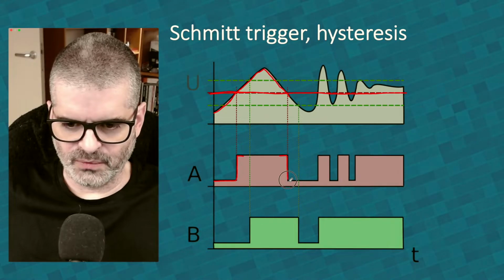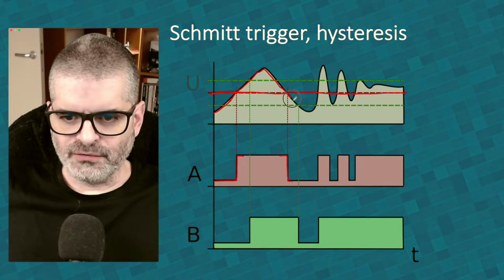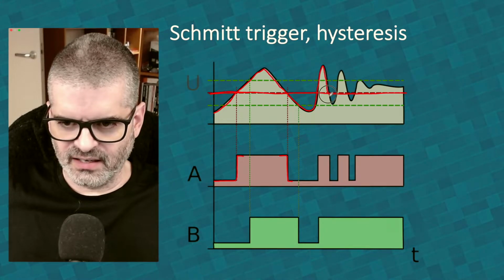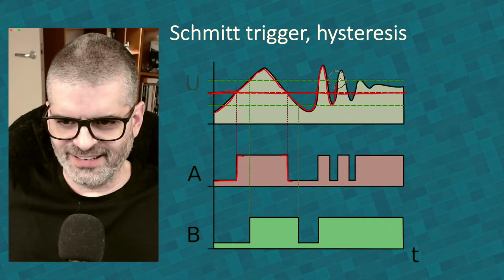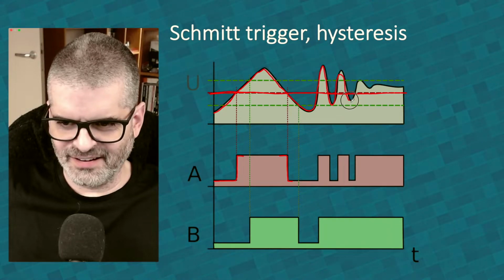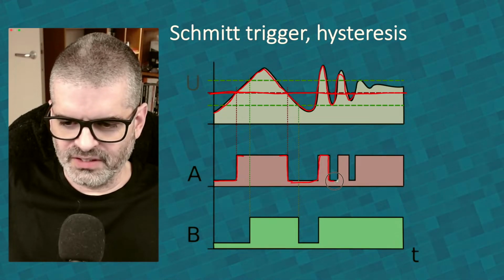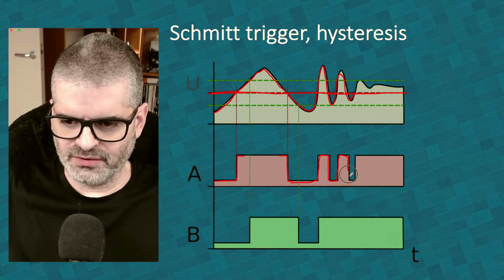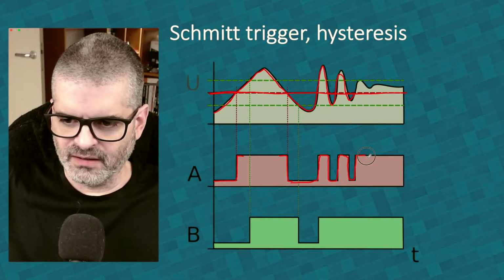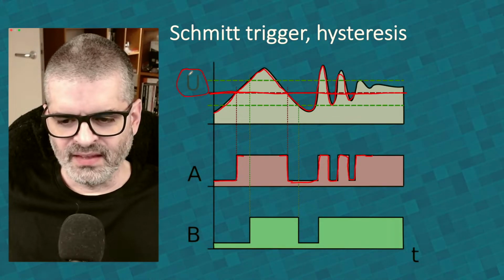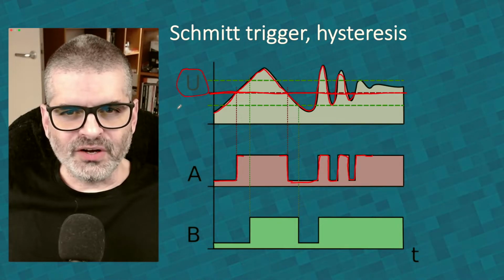The signal goes low again. And if you follow this, you see that it crosses the threshold here, then here again, then here again, and then there again, and here again. And you have this up and down on the digitized version, which is what the signal will mean for whatever chip is seeing this signal here as an input. And that's a very noisy input then.